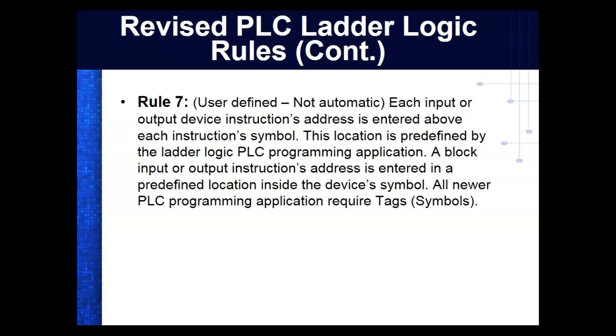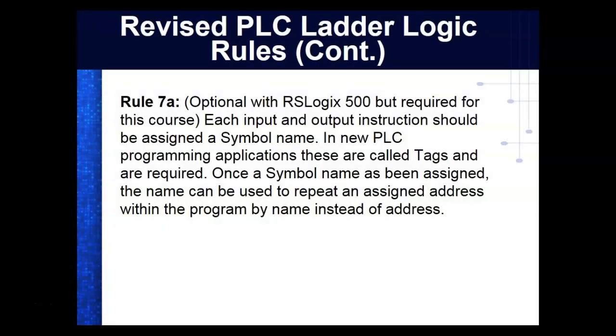This location is predefined by the ladder logic programming application. A block input instruction, which we'll get into when we get into counters and instructions. Block input and output instructions address is entered in a predefined location inside the device's symbol. All newer PLC programming applications require what we call symbols or tags. And we'll get into that. This is one problem I have with RSLogix 500. We'll show you. Optional for RSLogix 500, but this is going to be required in this class.